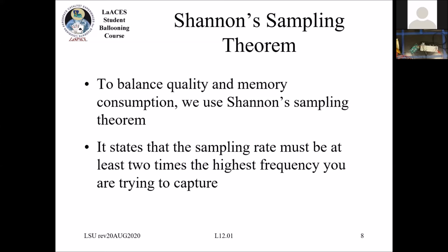So then I can look at things like temperature and pressure curves that compare the altitude to temperature and pressure. And from that, I can get a rate of change on temperature, pressure, other variables. Then I can also look at, well, how sensitive do I want to be? Do I want to be able to tell 0.1 degree changes or just 5 degree changes, right? If I'm looking for a smaller change, that means I'm going to need to sample faster.